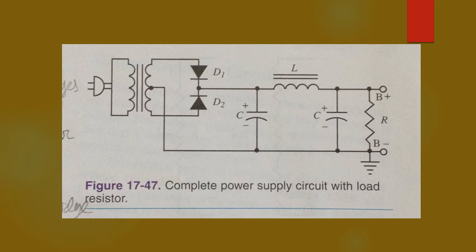During operation of a power supply, peak voltages are stored in the capacitors of the filter sections. These capacitors remain charged after the equipment is turned off. These capacitors can be dangerous if accidentally touched by a technician. The load resistor allows these capacitors to discharge when not in use. The wise technician will always take an added precaution and short capacitors to ground with an insulated screwdriver.